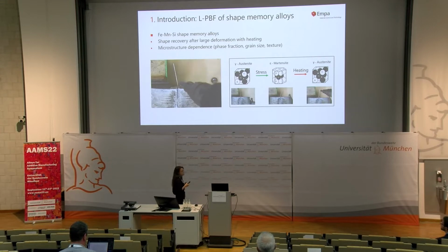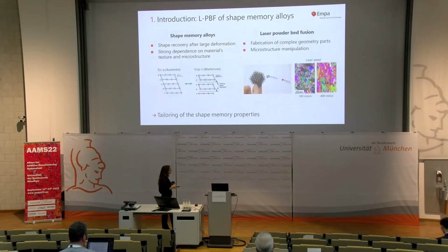One thing that we need to keep in mind is that the shape memory effect strongly depends on the microstructure. Microstructure means phase fraction, grain size, but also texture. So now maybe it becomes clear why we want to go for LPBF. Laser powder bed fusion is a technique that allows fabrication of complex parts, with intricate geometries and no limitation in the design.